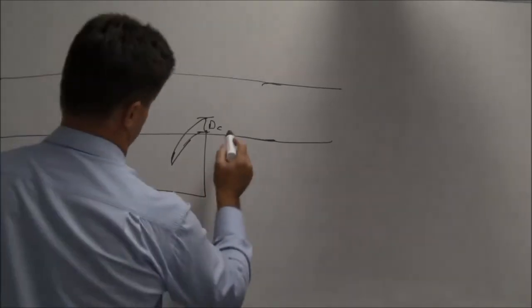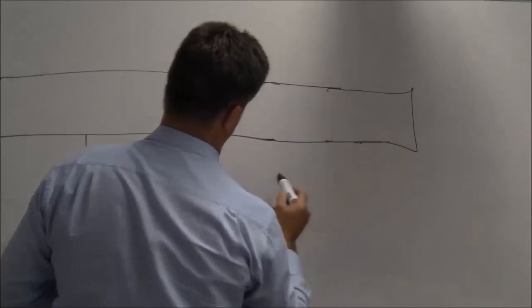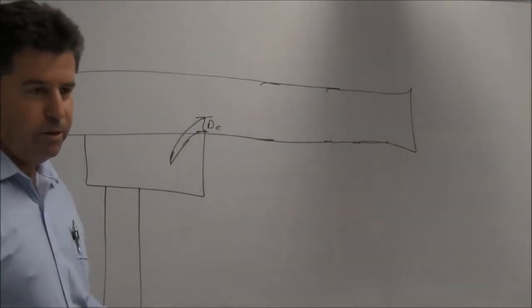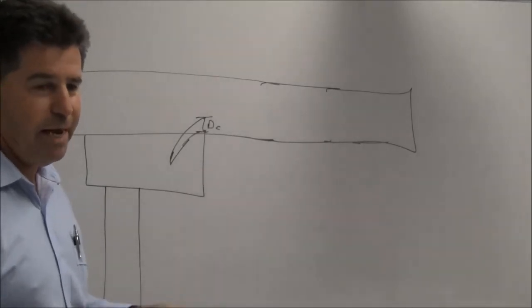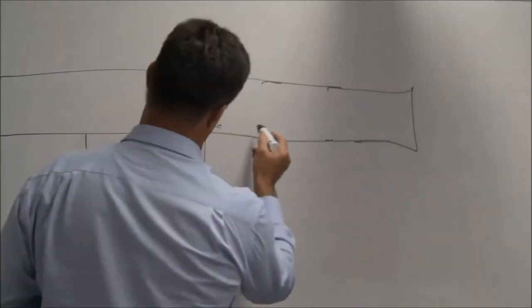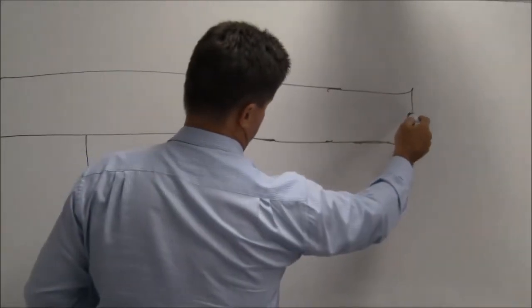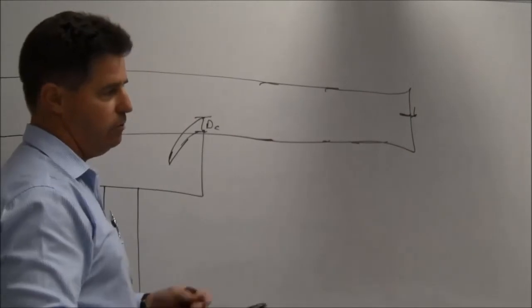Yep. Okay, the reason why it's doubled to the high end, basically, I don't know if you guys did any physics at school. It's a mass, so it's the kinetic energy of the water. To drive it, to actually force it through on such a flat surface, we need a head of water at one end, regardless of the length of it.